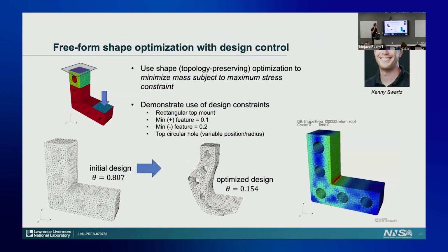So again, this was run through Serac, and Kenny's done a lot of work on essentially coming up with sophisticated ways of constraining the design space. So, for example, on the top surface here, this connection needs to stay parallel and fixed to the top, but it's allowed to slide along the top, and then a similar constraint here.